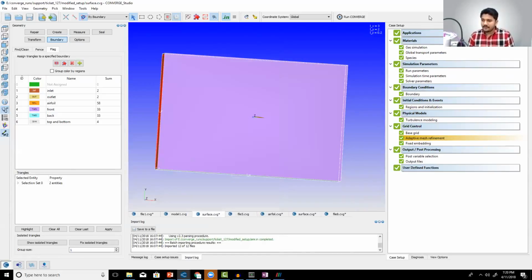Looks like we have a few questions. What is Y plus value? Y plus is basically a non-dimensional wall distance, Deepak. It basically says where are you with respect to your boundary layer? If your Y plus is less than 1, you are inside your boundary layer. You are in what you call the viscous sublayer, right? So if you have to understand Y plus correctly, try to understand the difference between laminar and turbulent boundary layers. You should be able to get it.